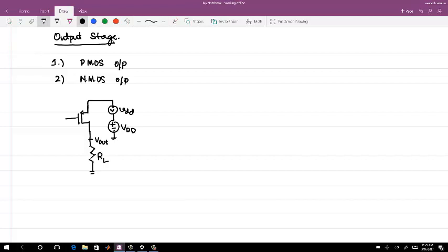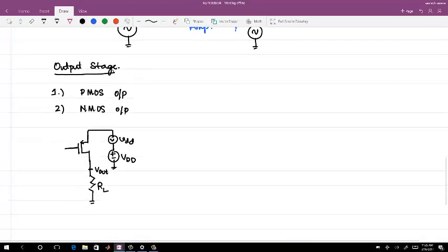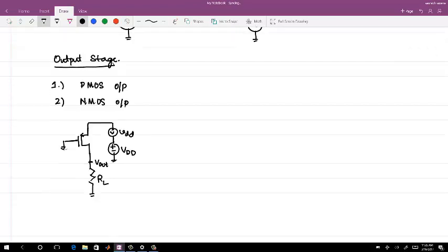Okay, and this is the gate node, right? In the regulation, there can be two conditions: the gate of the PMOS transistor is tightly coupled to VDD, or it is coupled to ground, meaning VDD doesn't affect the gate of the PMOS transistor. You can see the PMOS has three terminals; right now I'm not considering the bulk. The drain terminal is the output node. The noise is directly coming on the source terminal. It can happen that the gate terminal also sees the same noise, or it doesn't see any noise. So we consider both cases. One case is where it is grounded.